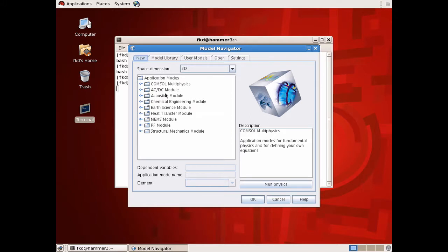And the other thing is that if we want to be able to couple problems, you'll remember that if we're solving the flow problem, we have something that looks like, depending on how we write it, storage times the change in head with time is equal to hydraulic conductivity times second order of head, and we have a system that looks like change in concentration with time is equal to diffusion second order concentration.